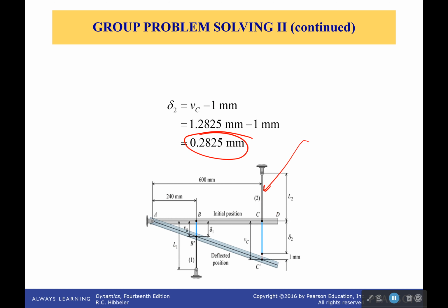Remember that we use similar triangles to solve these kinds of problems, and that our rigid bar right here is completely rigid. And we also assume that even though it's a rigid bar and it would probably be moving slightly to the left here, that it just goes straight down. That's the only way you can solve these problems, at least simply.